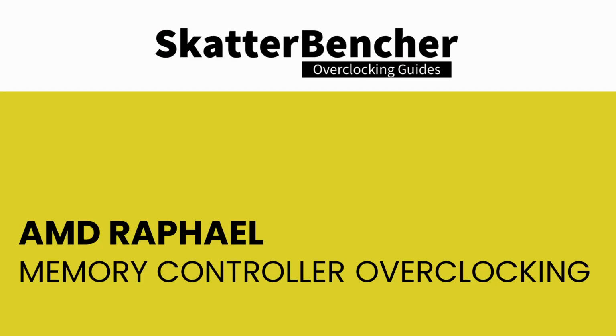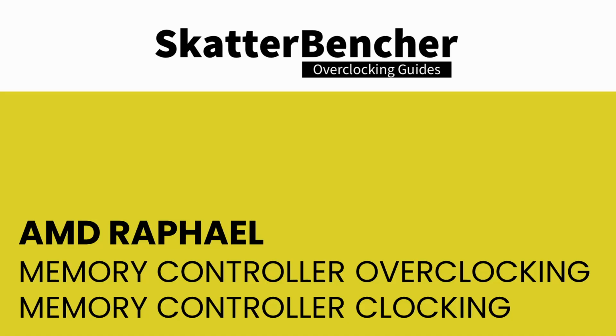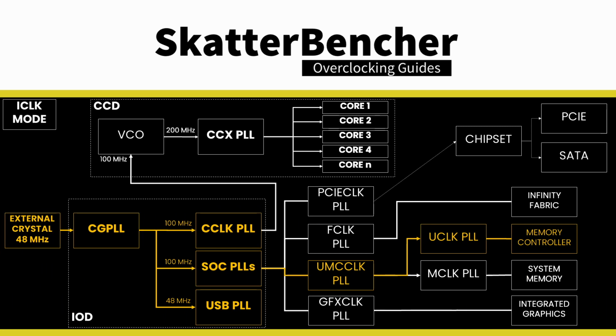AMD Raphael CPUs have 2 DDR5 Unified Memory Controllers, or UMCs, embedded in the I/O die. The memory controller should be able to support DDR4, but AMD has made it very clear that from Zen 4 onwards, it's DDR5 all the way. The Unified Memory Controller Frequency, or UClock, is derived from the UMC clock, one of the SoC PLLs.